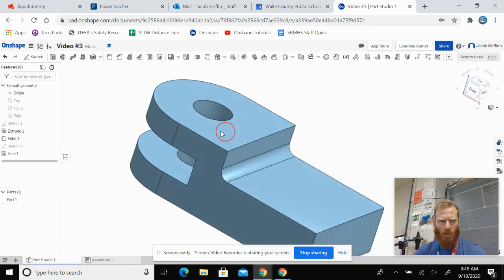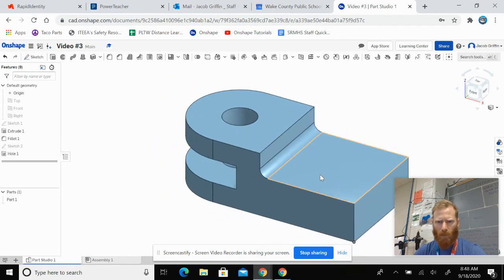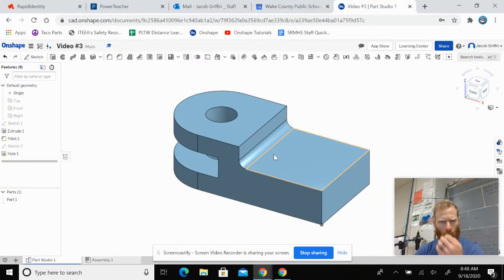All right, so pivot lock. This is something that we could have some type of strut or swing coming into here, and it bolts into this lock and allows it 180 degrees of freedom for movement. So it kind of swings around this way. So that's what we are constructing today. So now let's draw these back holes. So 1 arch, 1 counterbore hole, and that kind of gives us how we can attach this piece to the greater assembly whenever we get to that point.